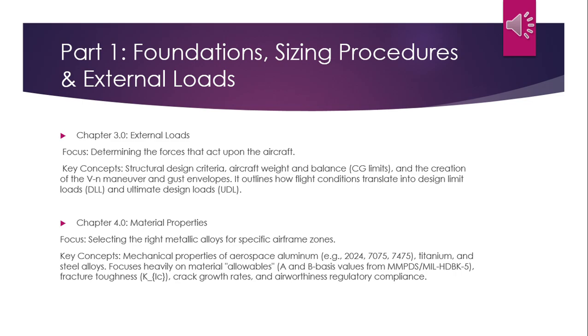The key concepts: structural design criteria, aircraft weight and balance, CG limits, and the creation of the V-n maneuver and gust envelopes. It outlines how flight conditions translate into design limit loads and ultimate design loads.